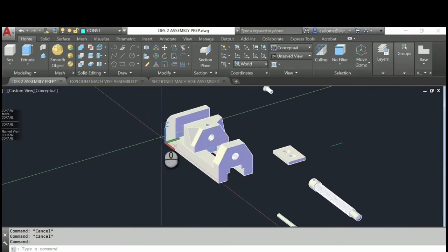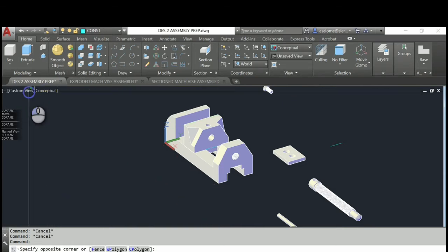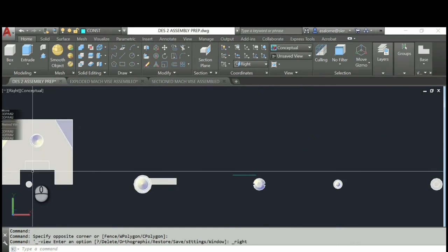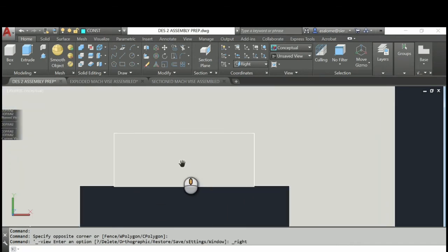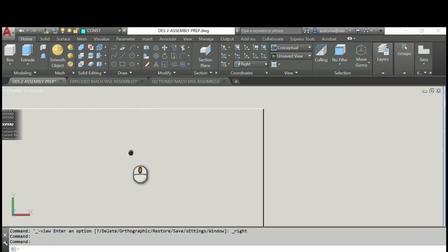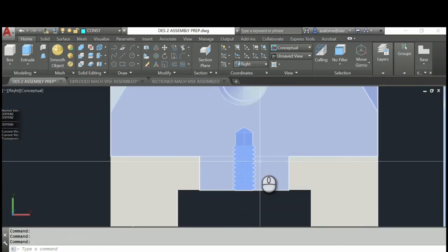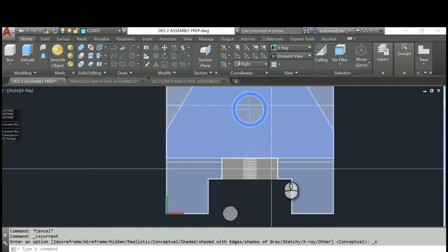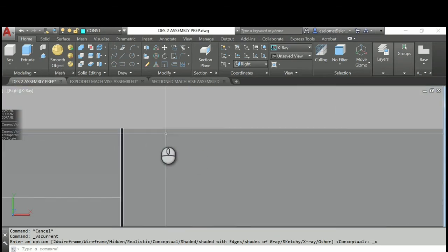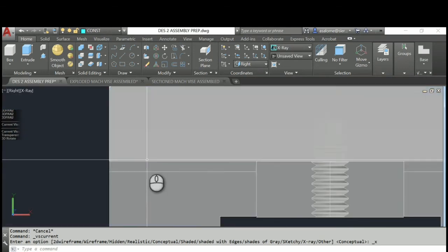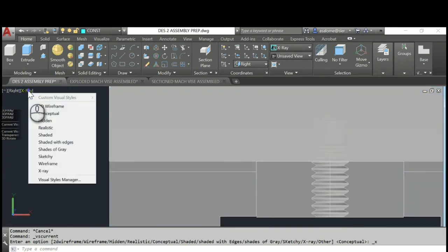And then I'm going to go to the right side view to double check my work. So I'm going to go right. That's going to give me a straight look at what's going on here. I like to make sure, oh, yep, I've got a gap there, I've got a gap there. Sometimes I'll go to X-ray mode, and that's going to depend on whether your computer can handle X-ray mode, to make sure that I do indeed have a flush mate here, and I have those little gaps on the side, meaning that it's centered. Okay.